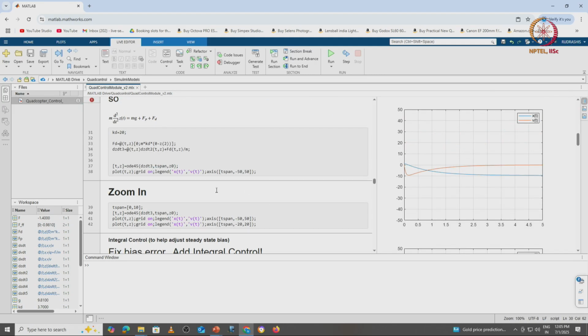So I am bringing in a small derivative control, proportional and derivative. You see what happens when I give an input: the velocity initially increases, then the velocity comes to 0. Because of that, my drone initially starts climbing, and once it reaches the 10 meter altitude, it remains stationary there. The PD controller helps me achieve my desired height.